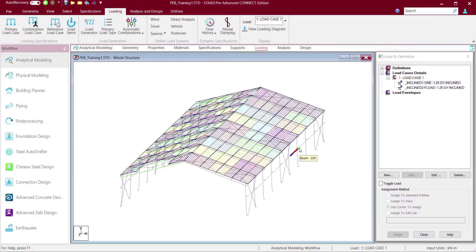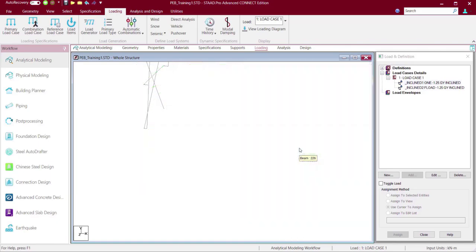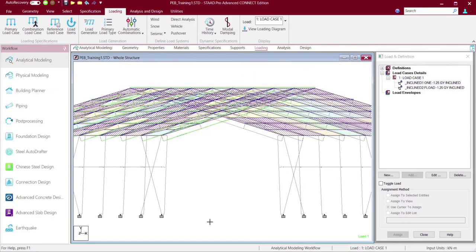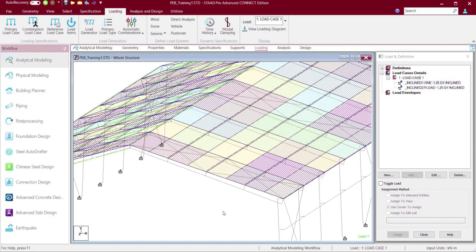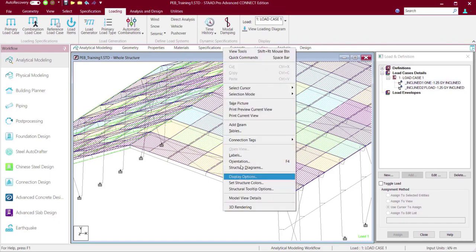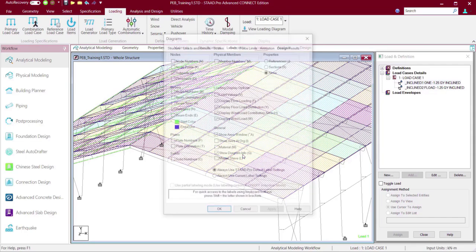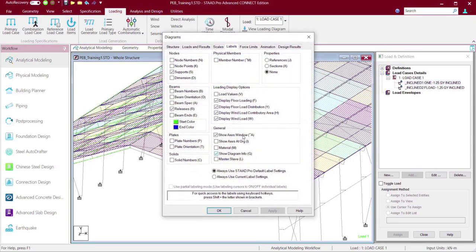Okay, now we have assigned for the first half. You can see the pattern, or the distribution pattern, of those floor loads is quite different from the left hand side, because in the right hand side only, I have modified it as a one-way distribution system. You can see the pattern is completely different. It's like the load is divided into two halves and directly being applied on the parallel members. The purlin is, in our case, these parallel members.